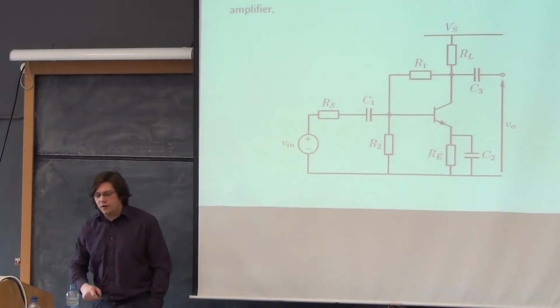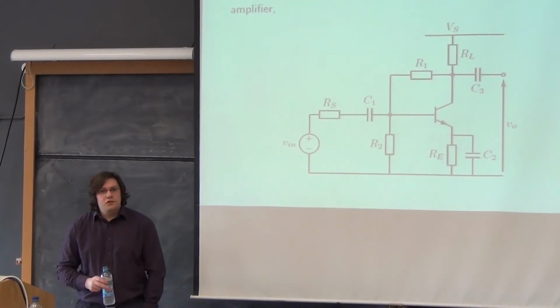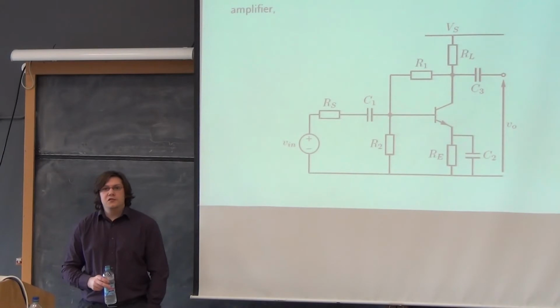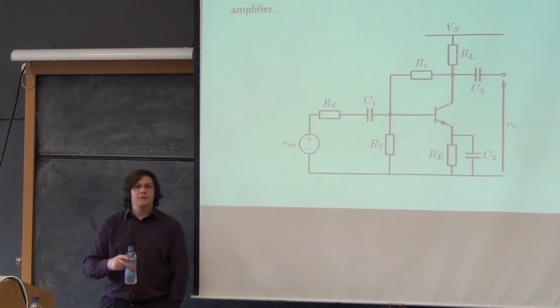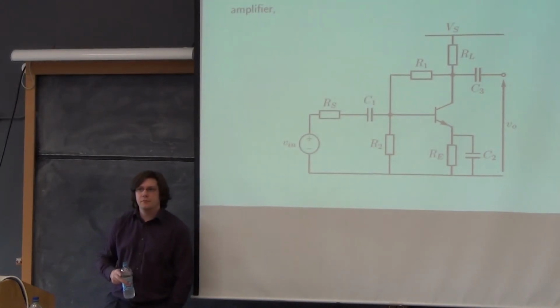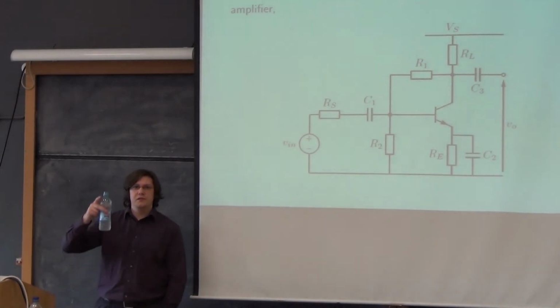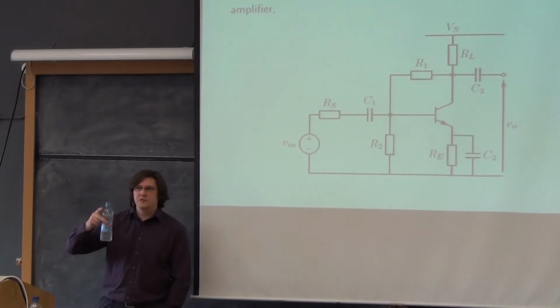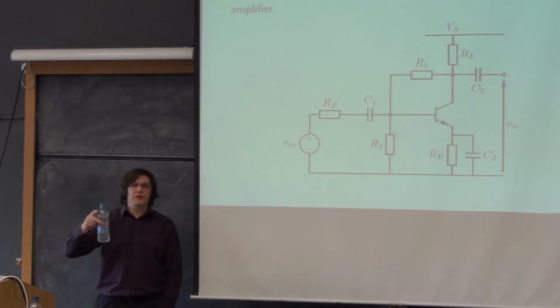It's the same set of arguments which are used in the construction project for why R15 and R16 look like they're in parallel when you're calculating the Q value for your second stage, where you've got that cascade of a JFET and a bipolar. R15 is biasing some push-pull stage from the supply to the base, and then there's another resistor from the base to the ground.